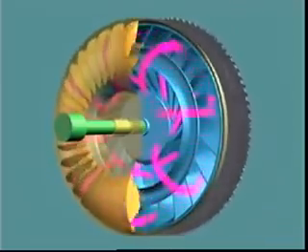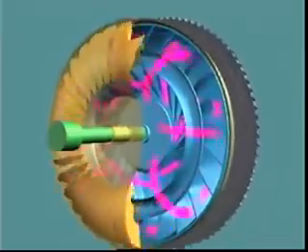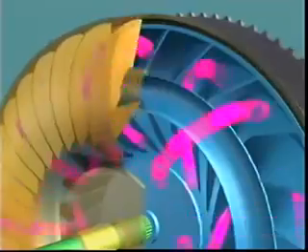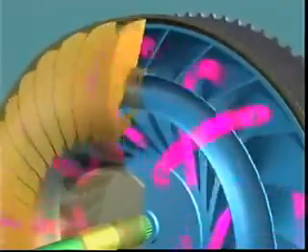When the engine accelerates, higher impeller speed discharges the fluid across and against the turbine vanes with greater force. Fluid exits the impeller at high velocity and enters the turbine at its outer edge. This exerts a turning effort against the back of the turbine vanes, which absorbs energy in the fluid, causing the turbine to rotate and transfer the drive to the transmission.